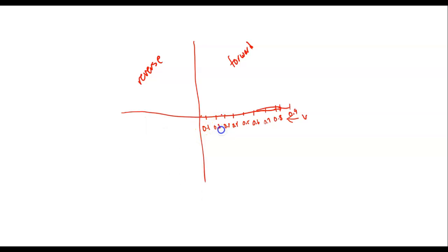If we were to measure the current, as soon as you put a voltage across here, we have a little bit of current like this. I'm sorry, this is I forward, and this is I reverse. When it gets to around 0.5, right around 0.6, it's going to start up, but it's not going to be vertical. It's going to be at a slight slant, which indicates that the voltage does change. The more current you put through it, the more voltage it drops.